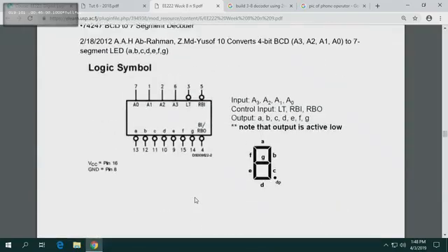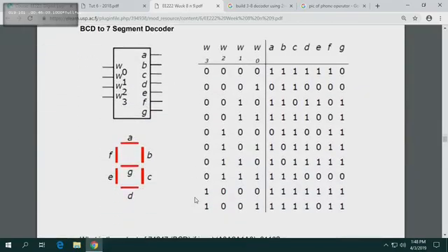So these decoders, guys, are very easy. If you have a lot of money, what else could we do? 4 inputs. Is there any other chip which we could use instead of using AND and NOT gates? You could use a 4 to 16 decoder to do A, one 4 to 16 decoder for each output. So you'll need 7 of the 4 to 16.